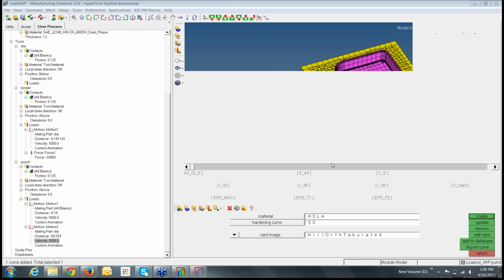That comes on your judgment. You cannot directly decide. You should be aware based upon the component which region of your component has to be flanged, when it should be flanged. You cannot do flanging operations first and do trimming operations later. You need to plan it accordingly such that you achieve your finished component within minimum number of stages.